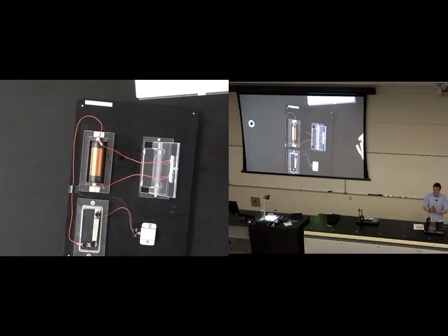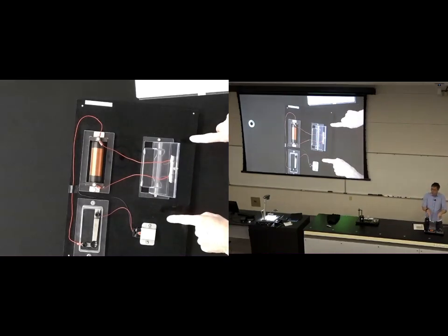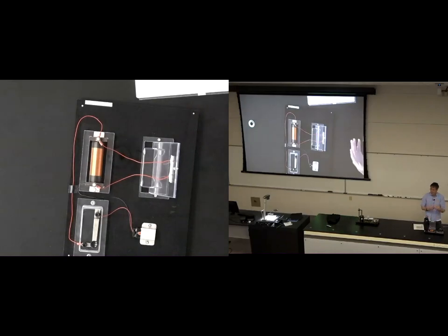Now, this has practical applications, you might be surprised to know. Cameras, we just use iPhones now, but cameras used to have flashes on them when you take a picture of your friends. Those flashes need a large voltage to flash that bright lamp. Well, the camera's got a 1.5 volt battery in it. It's never going to flash that lamp. This arrangement, where you can create a large voltage from a small voltage at the moment you switch it on and off, is what flashes the flash on one of those old-fashioned cameras. And so there was at least one application of this.